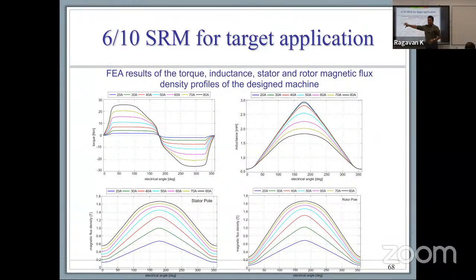You apply current in the positive inductance profile and the negative inductance. Basically, you're applying current here and you're applying current here. If you wanted to look at how the SRM operates, take each one of these phases, start stacking them together. If you add them together, you will get the resultant torque you're going to get.